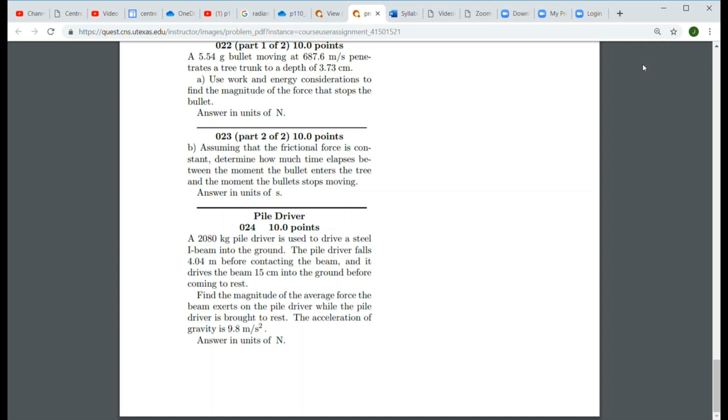So what you do is take a big hunk of metal, like a big, huge iron cylinder, raise it up with a crane and drop it so it slams down on top of the I-beam and it drives it a small amount into the ground. You keep repeating that over and over again, and you can get a huge beam really deep into the ground, which keeps it from ever moving after that.